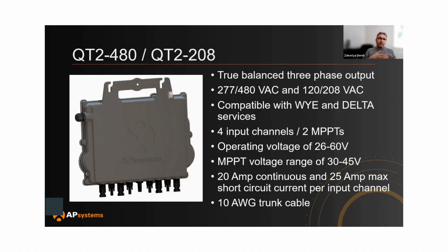They're compatible with the Y and Delta services. And this is one of the questions people ask, like, does it work with Delta? Because Delta doesn't have a neutral. Some inverters may not work without a neutral, but in our case, we can work without a neutral. So it is compatible with Y and Delta services. It has four input channels, as mentioned. It's a quad module, quad inverter. So you've got four input channels, but two MPPTs. So you've got two inputs in parallel, two inputs in parallel. Each goes to their own MPPT. We have a very wide operating voltage range, which covers most of the modules in the market today.